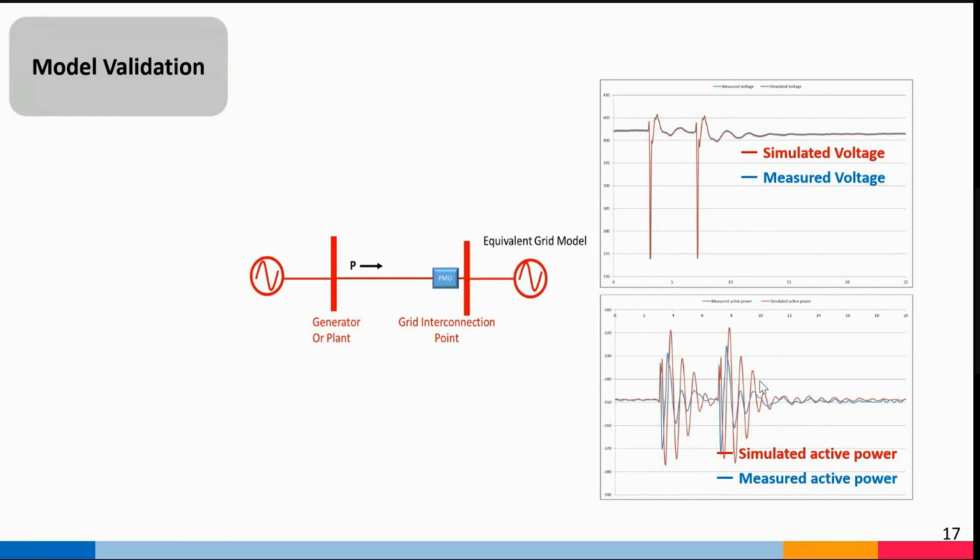So with this PMU data, let us say this generator is there, and I want to evaluate whether this generator has provided me the correct turbine system parameters and governor system parameters. So we can do a model validation of this particular power plant by utilizing the synchrophasor data. If there is a voltage or frequency change on the grid side, then the generator excitation, governor, everything will try to respond accordingly, and when they respond, their active and reactive power correspondingly change.